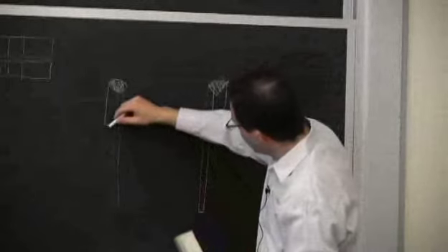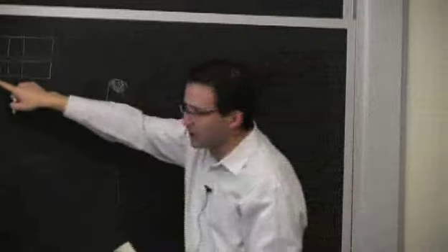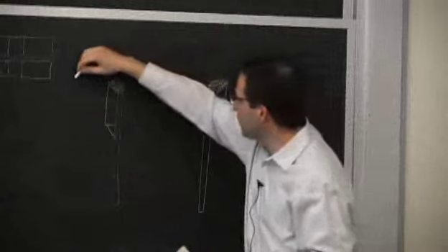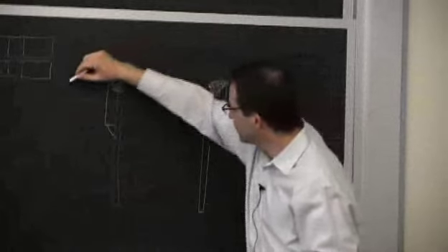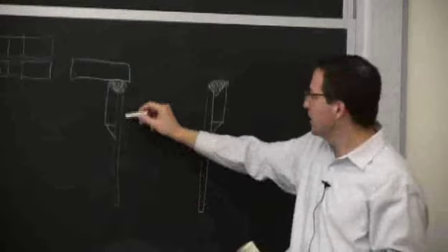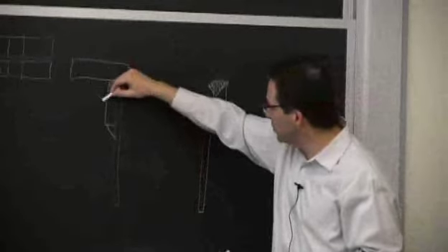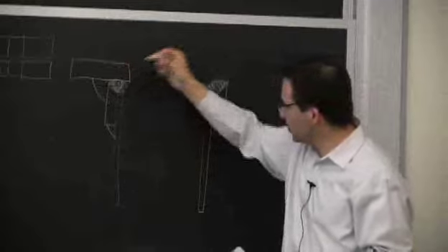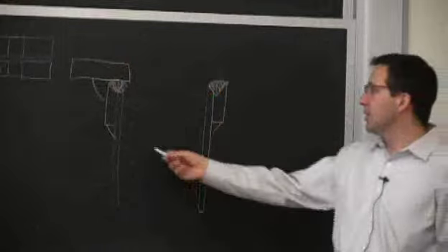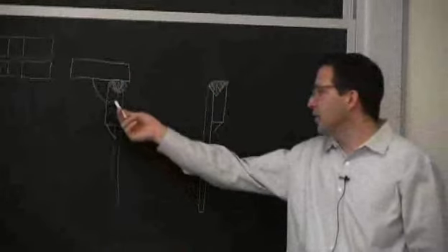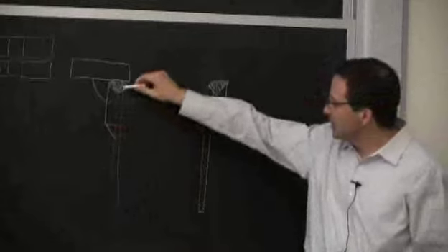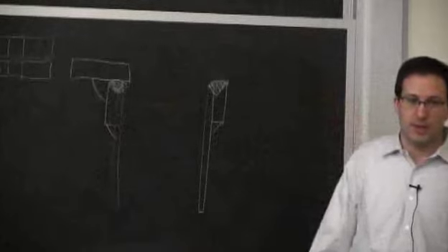Now, you end up doing the same weld that we talked about here. It's the same process. But now, when you put your flange over here, your highest stress zone has more material. So now when you put your bigger weld, you may have twice as much strength in that section at the minimum. Because not only do you probably want to count only on the thickness of this, but in terms of stiffness, the stiffener also plays a role.